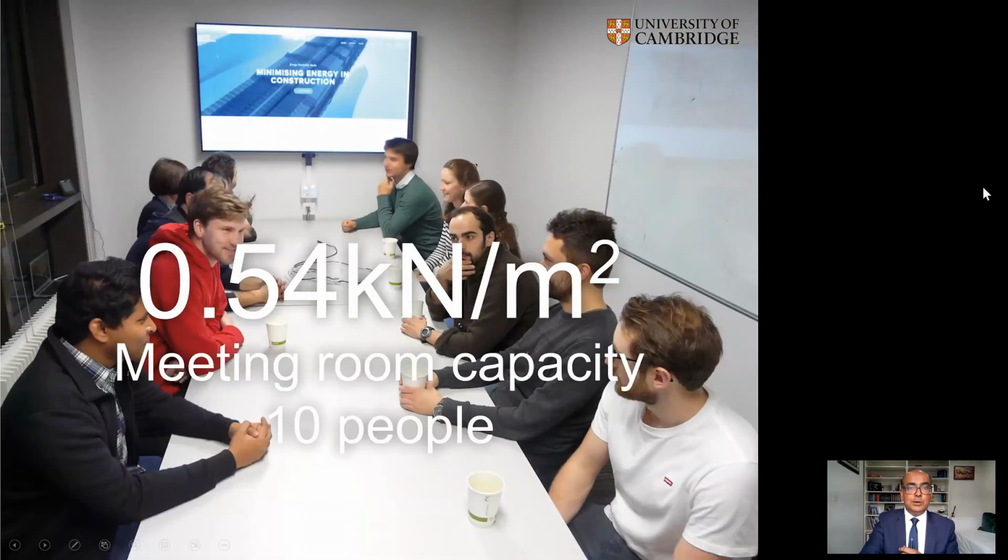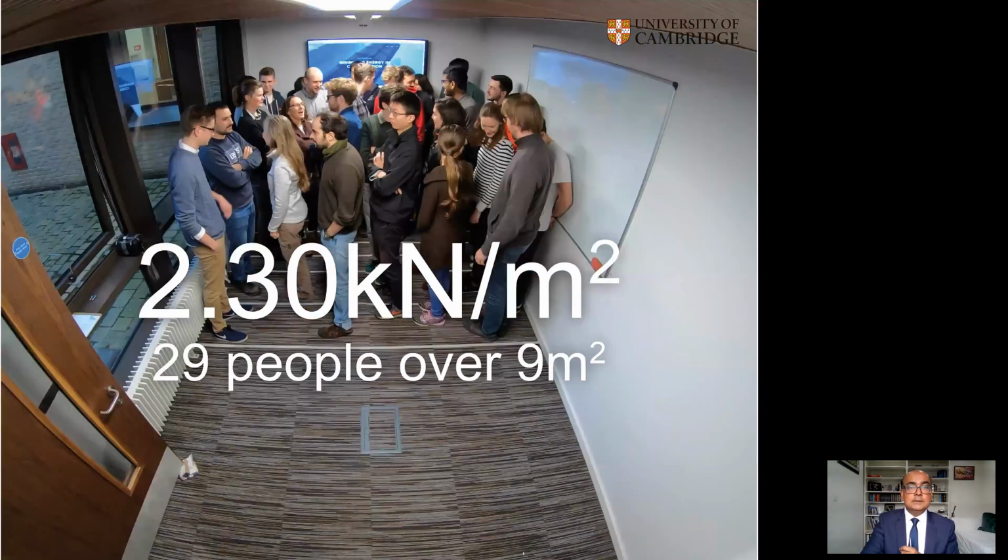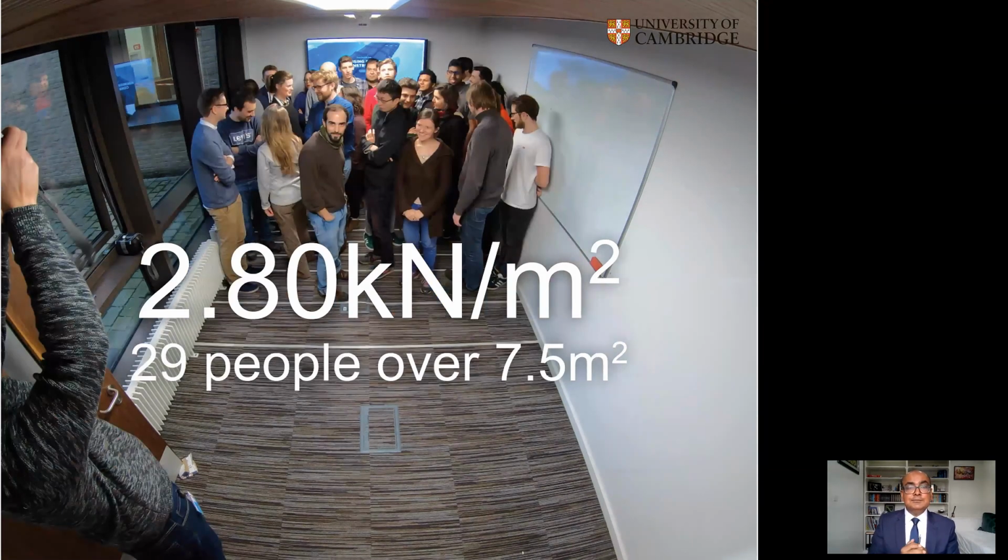Firstly, we have 0.54 kilonewton per meter square when there are 10 people sitting in the room, and it will look like this. Then we have 1.18 kilonewton per meter square, a full meeting room with 23 people. And then we have 2.3. Now people can't fit in, so they have to remove the table. And now we have 29 people over 9 meter square area. Then we have 2.8 kilonewton per meter square, 29 people over 7.5 meter square area.